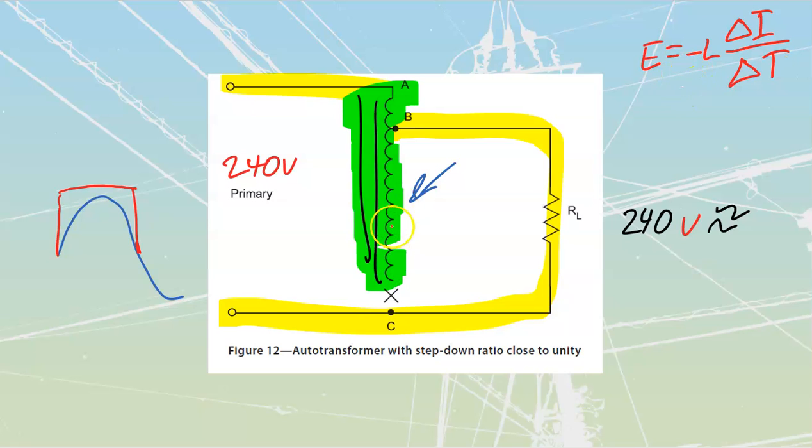And so what we get on this chunk over here is that every time we get this really, really rapid drop of current over time, this can be directly related to flux, right? The ampere turns that we have over here. We get this wicked fast drop, and that's going to generate a fairly high amount of voltage. You could also do it off of E is equal to BLV. You're going to have a really high velocity in the drop of your magnetic field as it switches over from one side to the other, which is just going to kick out massive amounts of voltage.